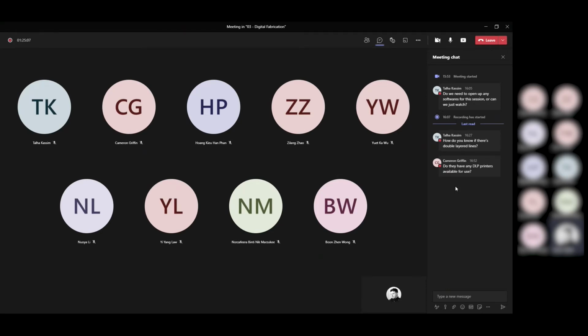But the key thing that I would recommend you do is explode your drawings, so you get them back to all individual lines or components, and then use those commands I was saying about earlier. In AutoCAD, you would be using the overkill command, and that will help you to remove duplicate lines. If you're in Rhino, then you could again use SelDup, which is short for select duplicates. You could also use Make2D in Rhino.